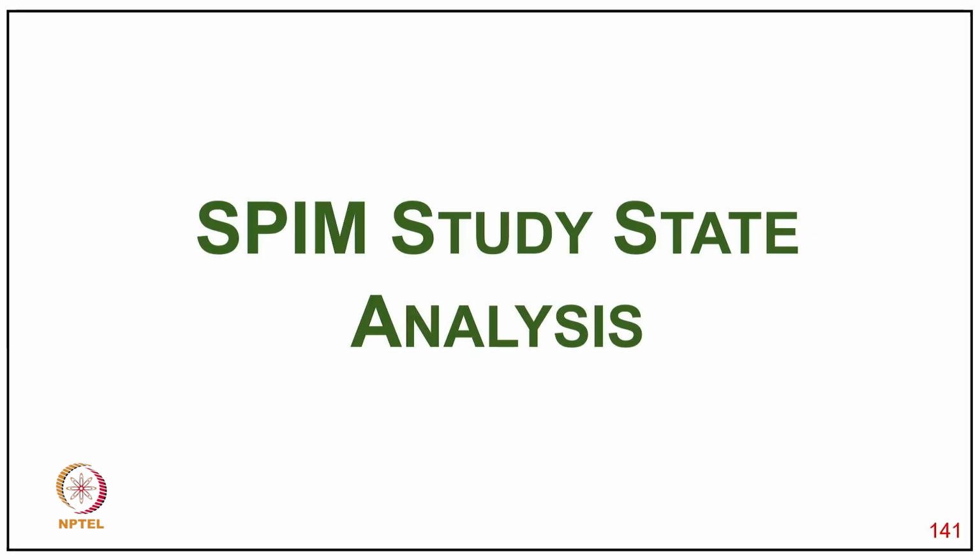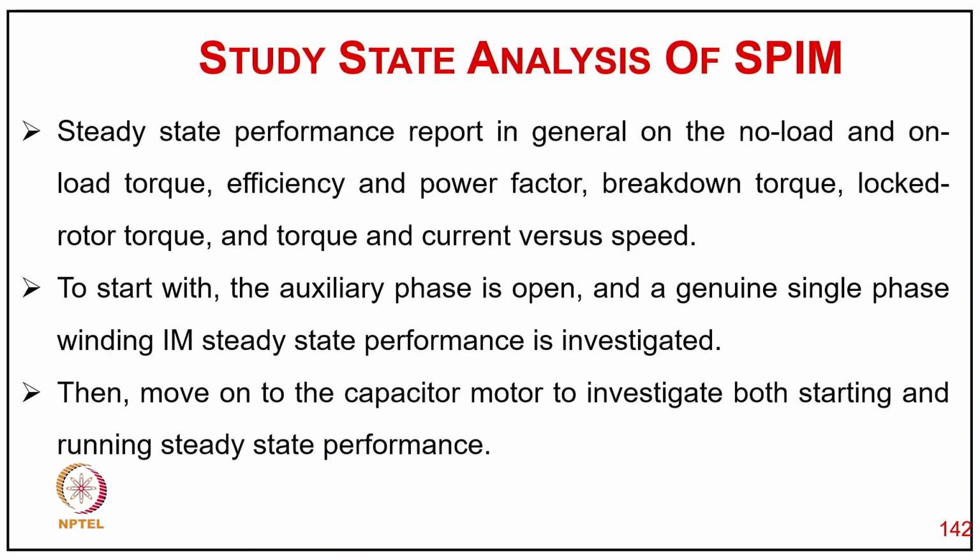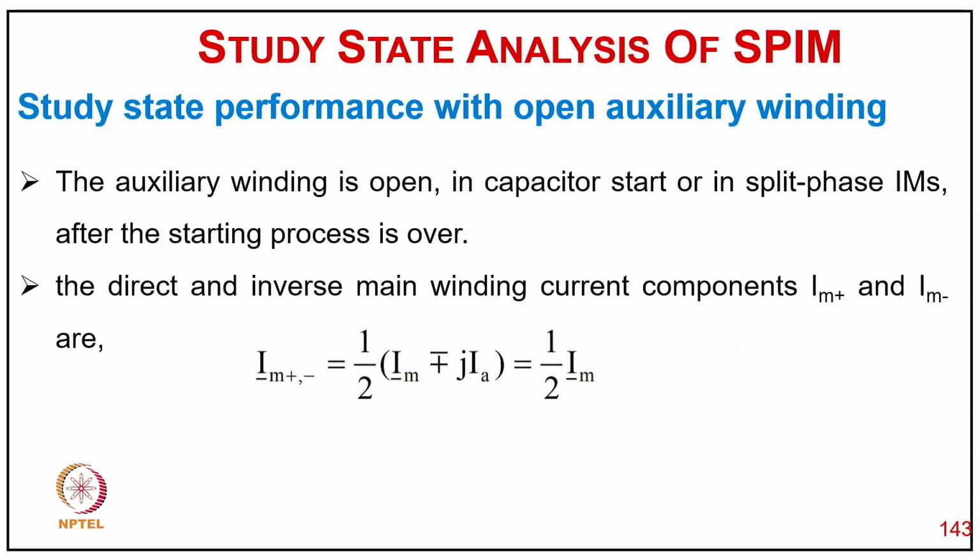Now coming to single phase induction motor steady state analysis. The steady state performance is reported in general on no load and on load, the efficiency and power factor, breakdown, locked rotor torque and torque characteristic. To start with, with the auxiliary phase open and a genuine single phase winding, the induction motor steady state performance is investigated, then we move to the capacitor motor to investigate both the starting and running steady state performance.